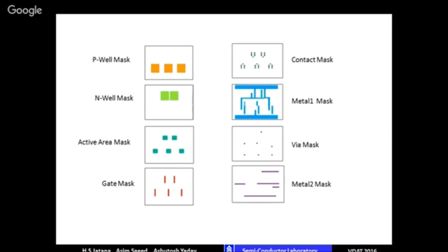Then finally you have to make contacts. You can see these are the contacts. This one dot you are seeing, on this line, is a gate contact. And as I told you, for this transistor, you see this is a diffusion. The definition of a transistor is a poly which will cut the diffusion. So this polyline is cutting the diffusion, so it becomes a transistor, and you have to make contacts as we are making here. And then finally by metal you have to connect these. And if there are two metals, you take a via and go to the second metal, and things like that.